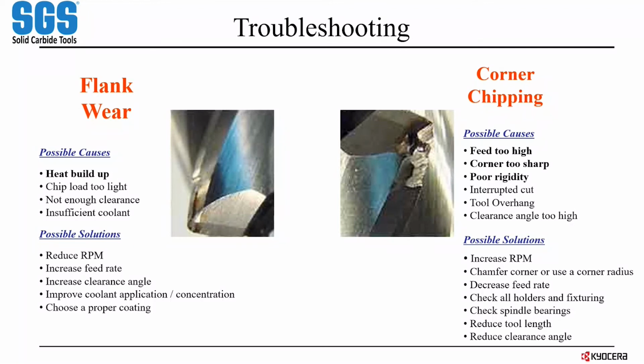If all of that's dialed in, then it could be a coolant thing. Getting more coolant to the cut, checking your concentration, or even checking to see if you have the right coating. There may be a better coating that's suited for that material.